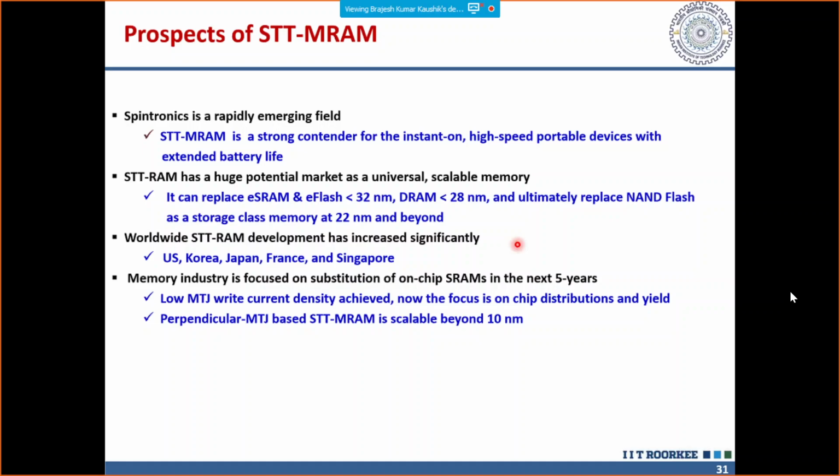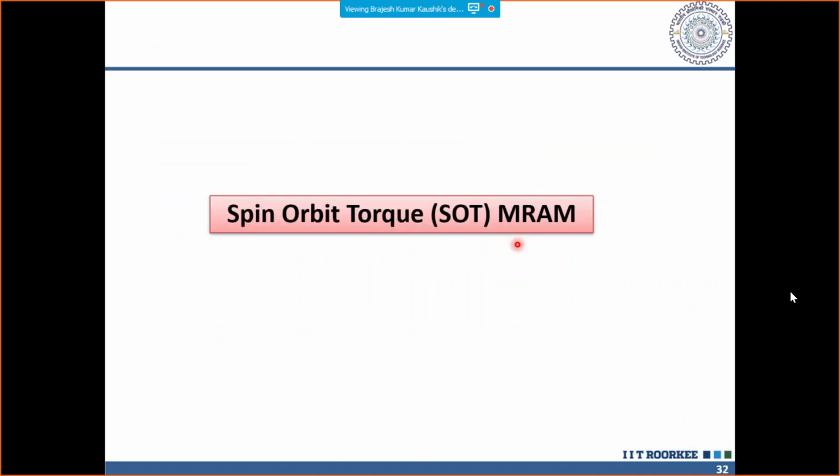If you talk about state of the art research which is going on, people are talking about MTJs being switched by laser pulses, and that is going to reduce the switching delay a lot. That way, the speed of these devices would be really wonderful, much higher than what we expect with even SRAMs. So this is another class of device that we have.